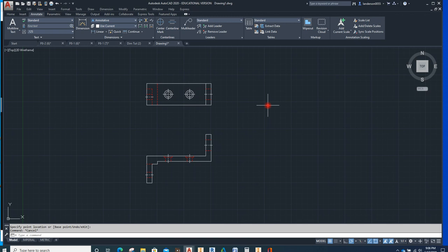So with that in mind, if we look at it this way, you're going to have a hidden line there and a hidden line there. Whereas if you look at it at this direction, you're only going to have a hidden line right there. Now this is not counting these guys because they're going to be in both views, okay, on both sides. So we want to draw it on this side, okay?